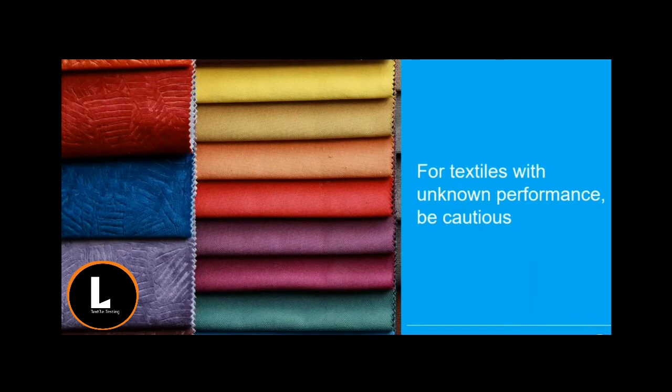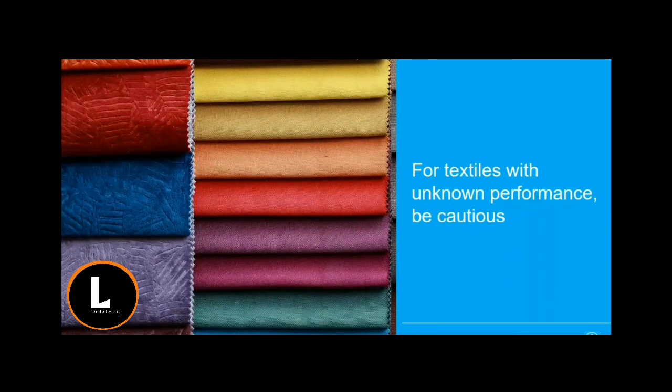It is a little easier to judge the testing step time duration for tests like method 2, where blue wools are used as a guide, as you have an idea of how long the blue wools actually take to fade. However, caution should always be taken when setting the timings, and we advise creeping assessments up to these fade steps.